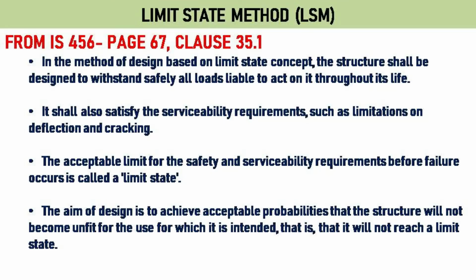Slide 14. From IS 456 page 67, clause 35.1. In the method of design based on limit state concept, the structure shall be designed to withstand safely all loads liable to act on it throughout its life. It shall also satisfy the serviceability requirements, such as limitations on deflection and cracking. The acceptable limit for the safety and serviceability requirements before failure occurs is called a limit state. The aim of design is to achieve acceptable probabilities that the structure will not become unfit for the use for which it is intended, that is, that it will not reach a limit state.